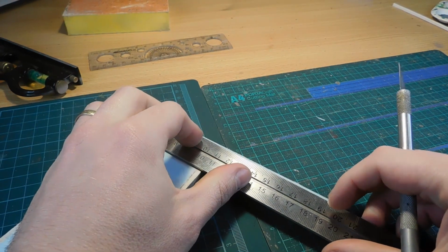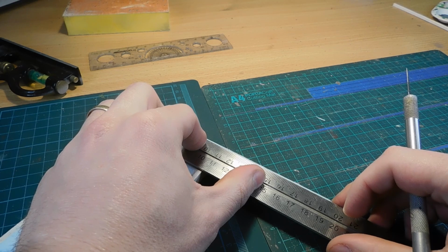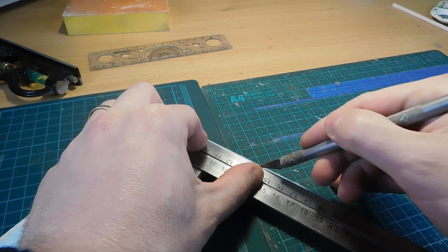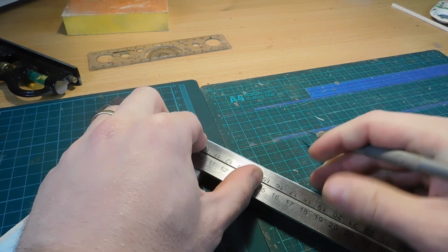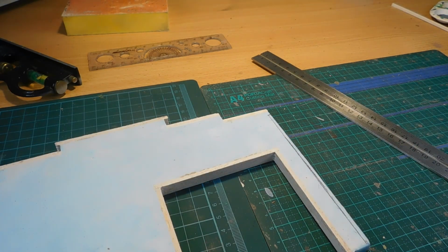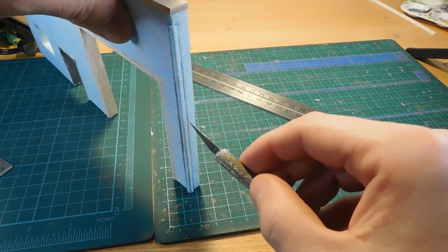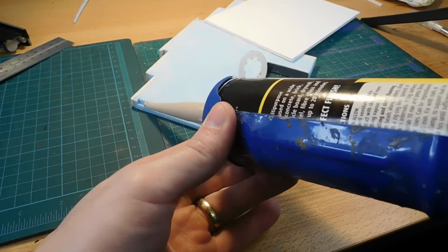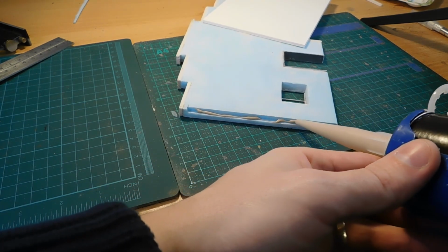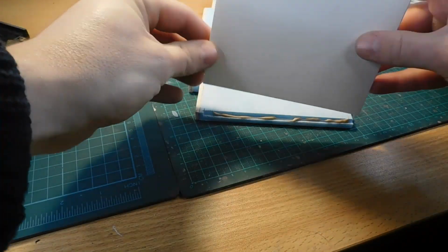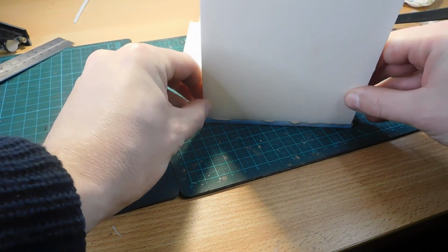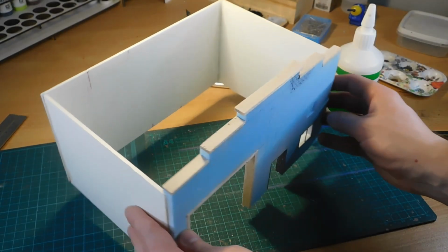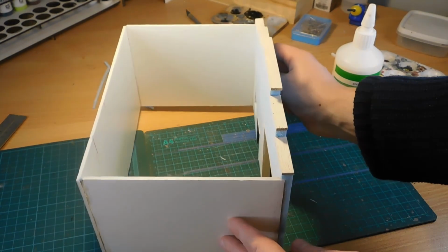Next, I cut a 3mm wide, 12 cm high slot into the very edge of the back side of the facade for the exterior side walls to slot into. Then, using a bit of wood glue, I fixed the side exterior walls to the facade, making sure that the side wall is flush with the edge of the facade. I do this for both sides and glue the rear wall onto the back to complete the exterior walls for the building.